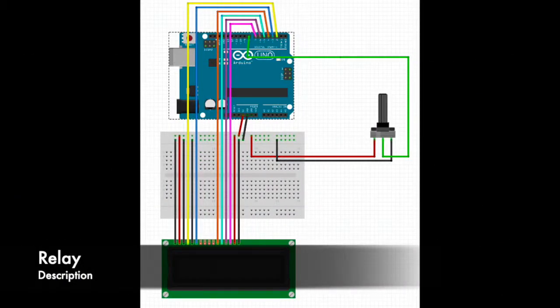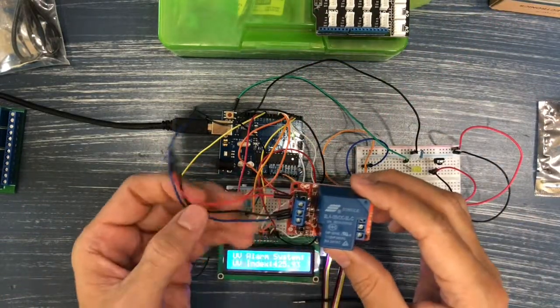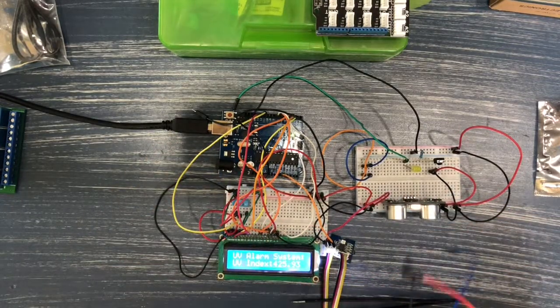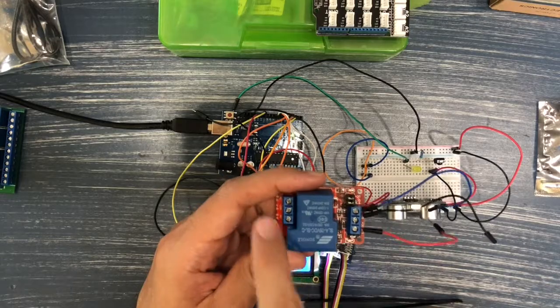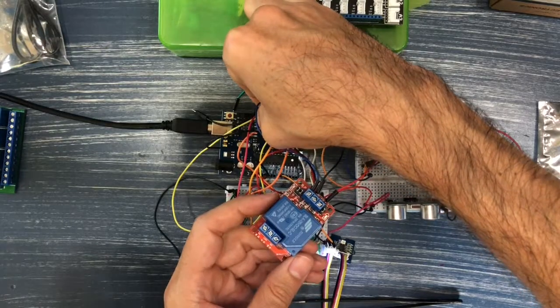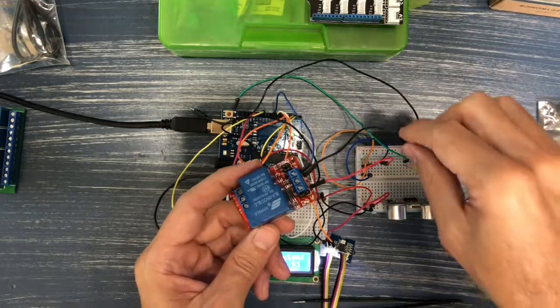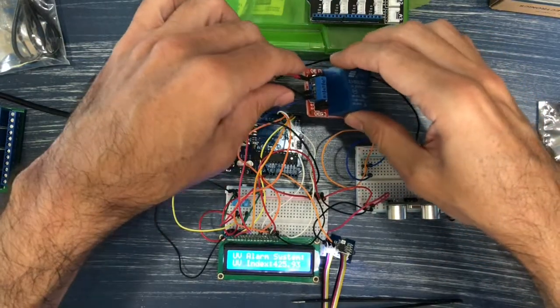So we're going to be connecting a relay, and a relay is basically a connection between an acting device with a signal pin. So what we have here is a typical relay, and I'm going to be wiring this up. It's very simple. As you can see, we've got positive and negative and a signal cable. This is the signal cable, this is the low side, and this is the high side of the relay. So the low side is the 5 volt DC one. So we're plugging it into pin number 8. There it is, and now we simply give it power. So 5 volt positive and ground negative. Let me place this over here.